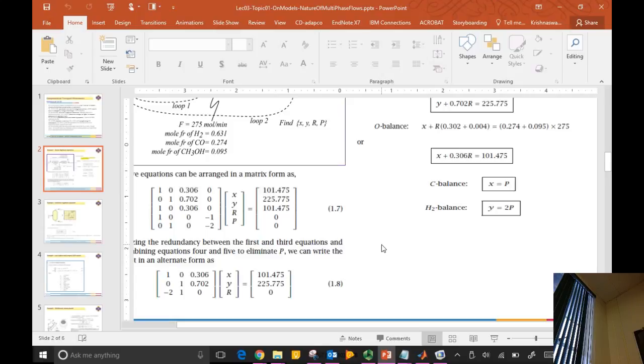If you built this 5 by 4 matrix and then asked for the rank in MATLAB, it will tell you if the rank is 4. But you can still use the backslash operator and try to find a solution to this in MATLAB. What it will do is try to find the solution in the least squares sense using this idea of a generalized inverse. The theory of linear algebra is very well developed for problems that are non-square. Right? Those are all built into MATLAB, but I don't think COMSOL knows about it.